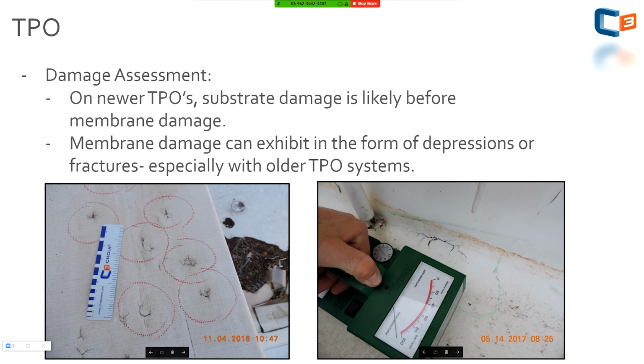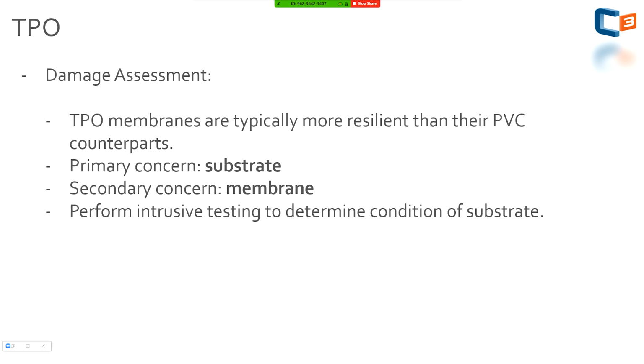Do not let another party come up here without the right tools or without cutting this material to tell you that this can be repaired just by heat welding a new membrane over these areas or a new curb flashing. So get ahead of that. If you have a Tramex moisture meter or you can cut these, do it. And in this case, it was a fiberboard substrate. The whole field of the roof had water, had a water-soaked membrane or a substrate type.